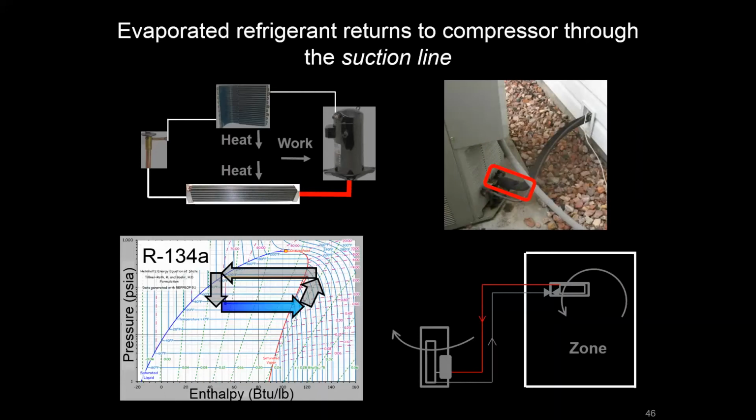the compressor, and you can see that it's insulated, and one reason that that's done is to protect the compressor. The compressor only wants to see vapor. Pumps are for liquids, compressors are for gas. So if there was any type of heat exchange at that suction line, such that there was a little bit of liquid getting into that compressor, it's going to cause damage. So we insulate it to protect the compressor.